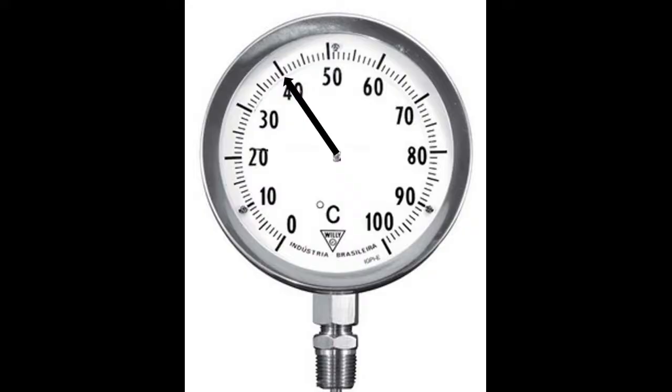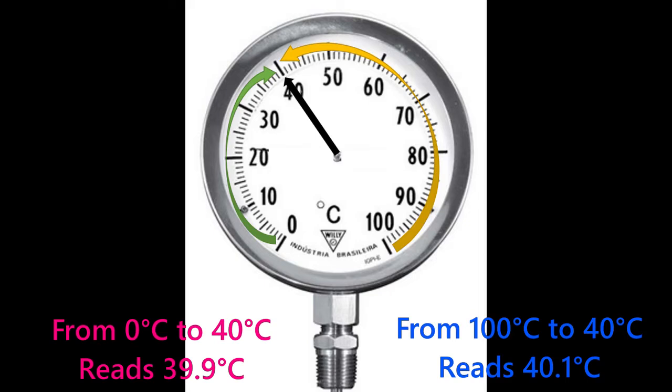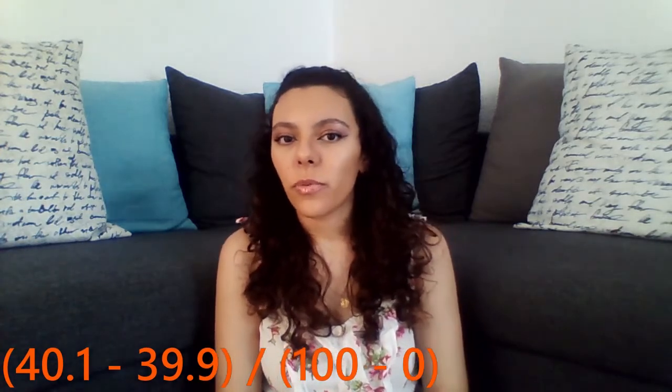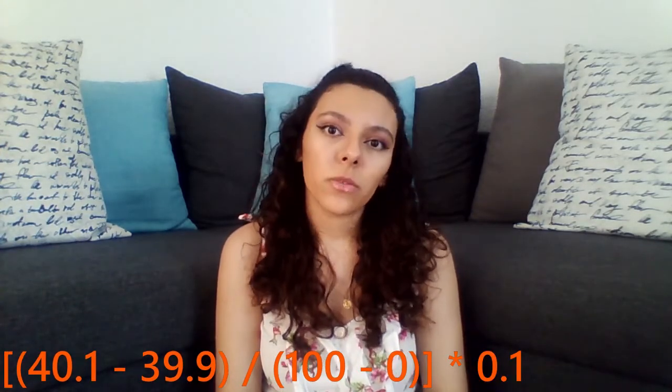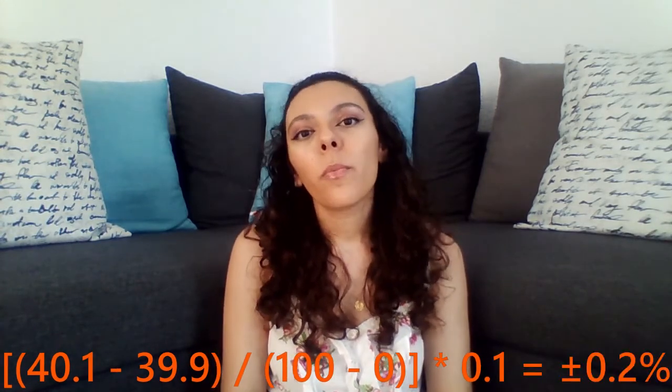For example, if we measure a variable of 40 Celsius with a thermometer with a measuring range of 0 to 100 Celsius, let's say the thermometer marks 39.9 when we measure from 0, and it measures 40.1 when the temperature drops from 100. Then hysteresis will be calculated by dividing 40.1 minus 39.9 by 100 minus 0. This all multiplying it by 0.1, which will give us a hysteresis of plus minus 0.2%.